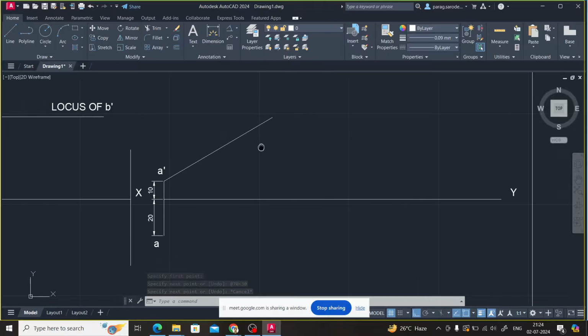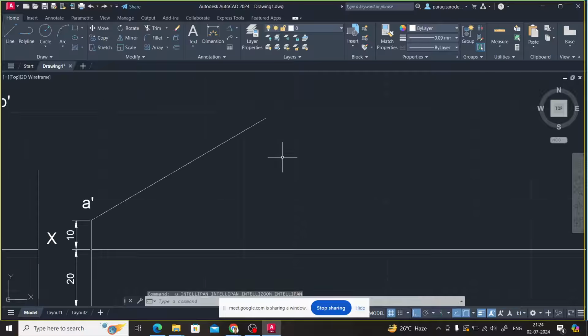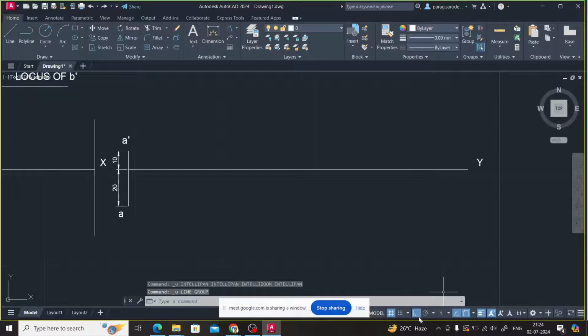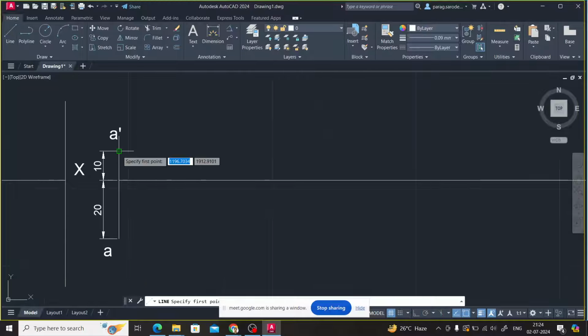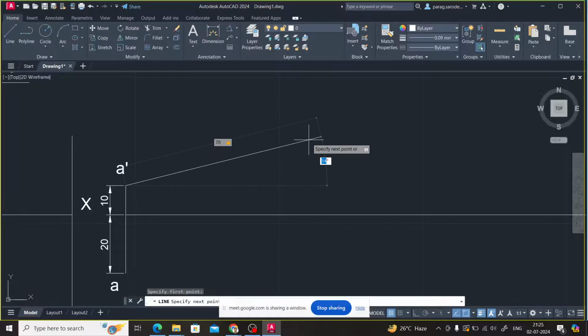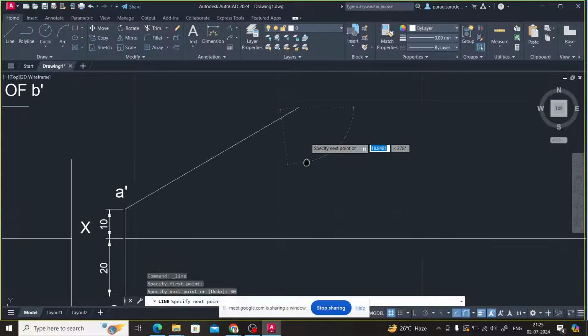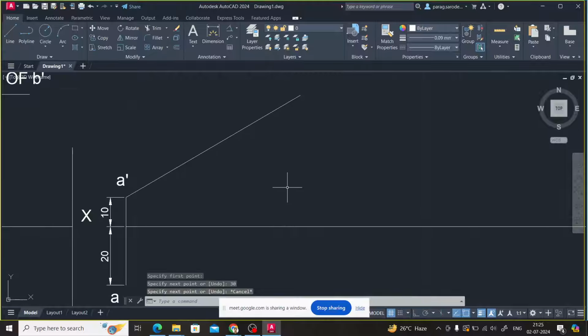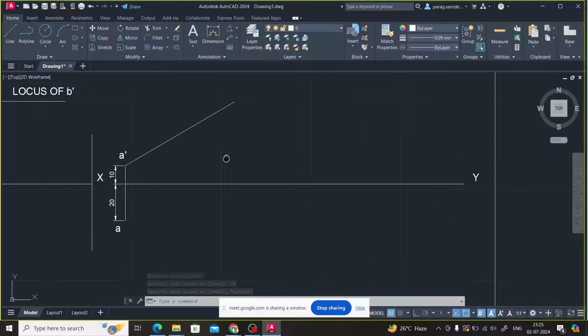So when you type 70, did you press enter or directly press shift and less than? I'm currently switched off the ortho. I will type 70 from the keyboard. I can press a tab. Once I press a tab, you can see this. Once I move the mouse, I can see the angle which is displayed on screen. In the direction in which I want the angle, I can type the angle, which is 30. So automatically the line will shift to the angle of 30 degree.